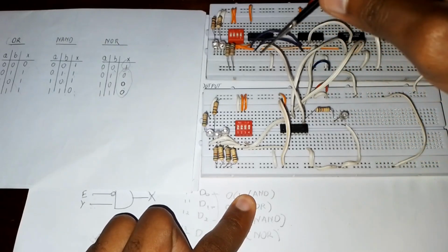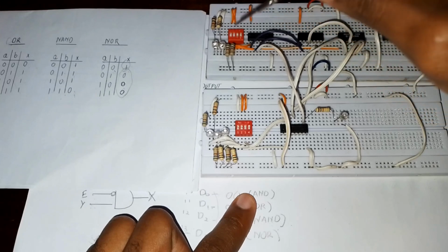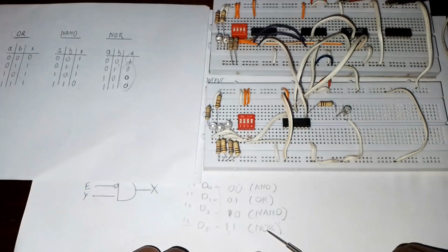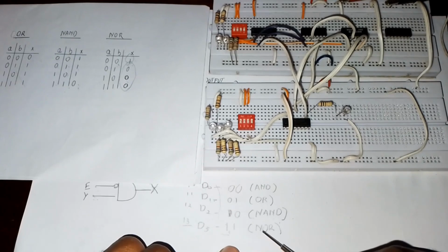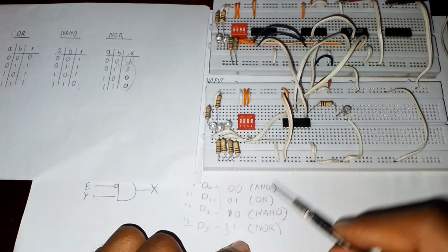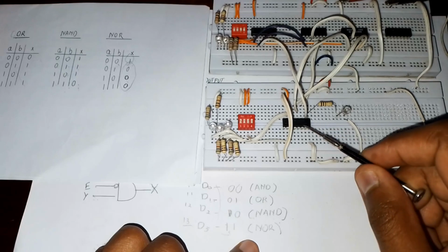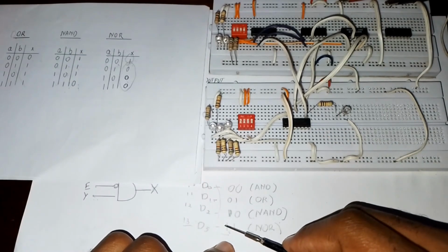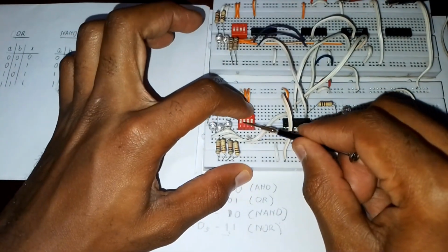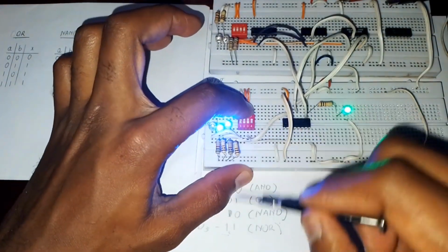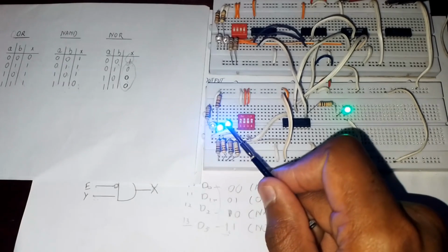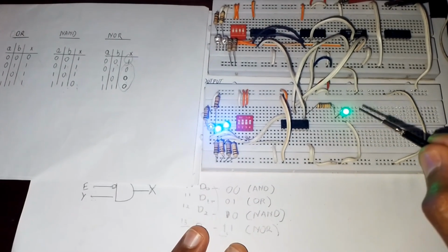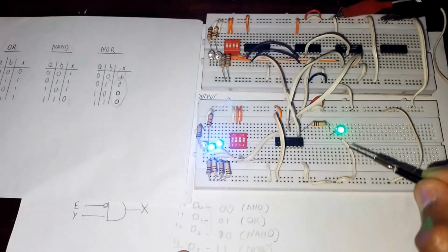So the output of the AND operation is 0 because both inputs are 0. That's why it's going to give you a 0 output. Let's go straight to our NOR operation. For us to select NOR in our multiplexer, we give it a code. It has its own special code. We have given it 11. So let's put 11 on our select. Yes, so our select has 11. So we have chosen the NOR operation, and we expect to see the NOR operation on the output.